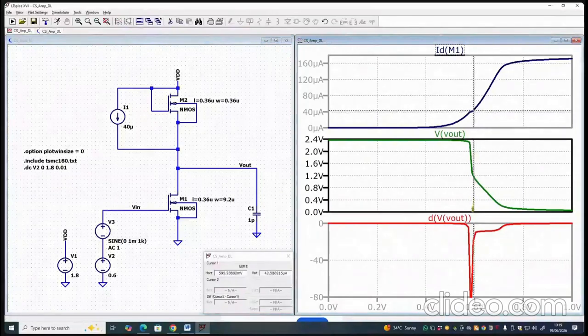Using a diode connected load. Sir, until today we were taught that we cannot achieve this. If you use only a diode connected load, that's why you are learning a new thing: how to increase the gain of a common source amplifier with diode connected load. So if you add a current source in parallel like this, you shall go and see that section in the Razavi's book.